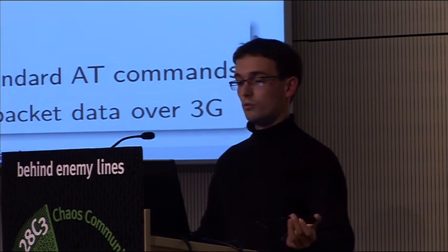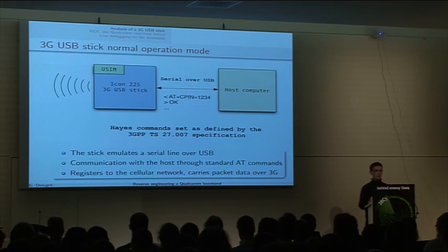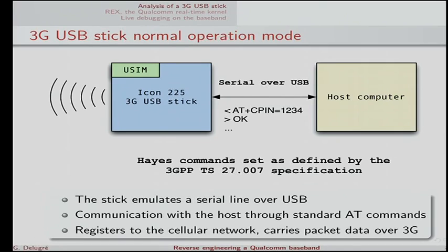So, if you plug a USB stick into your computer, what happens? Basically, you have this emulated serial port over USB, which allows you to talk to the stick and pass AT commands. For example, AT+CPIN=1234 to unlock the SIM.